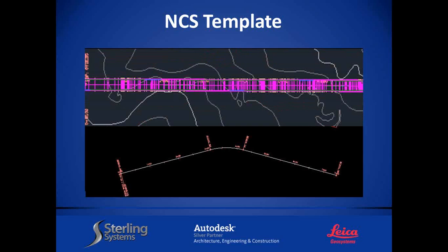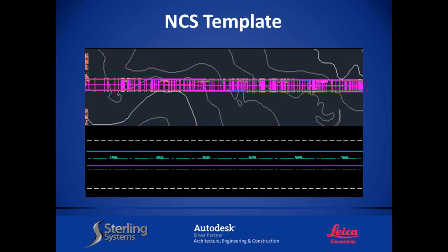Inside Civil 3D, we can also create corridors. Out of the box, this is what it looks like. We're going to jump into this too. This talks about code set styles. Inside code set styles, they use links. Links are great for design, but I don't want to plot them and I don't want to use them. So how about as soon as I create that corridor, it would look like this. Or maybe we change the colors to look like yours. But you see there's a huge difference. And this is what it takes to make Civil 3D work for you.